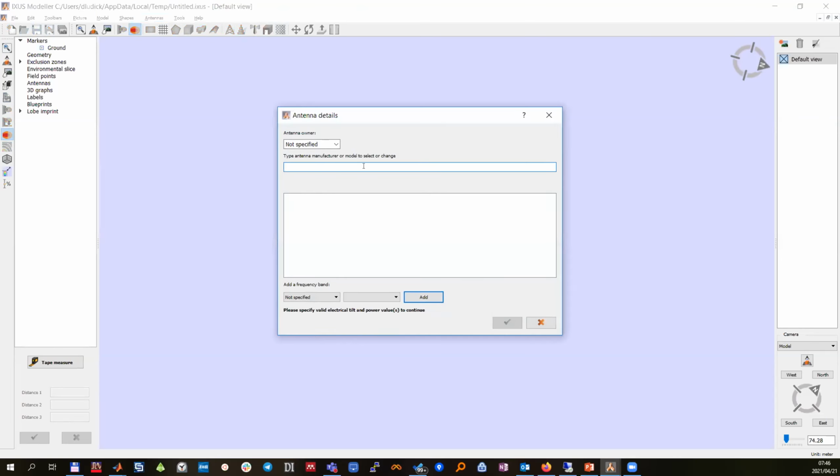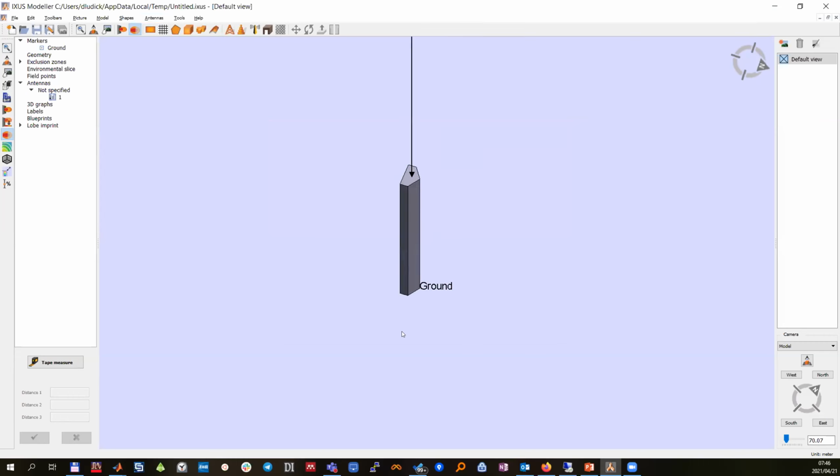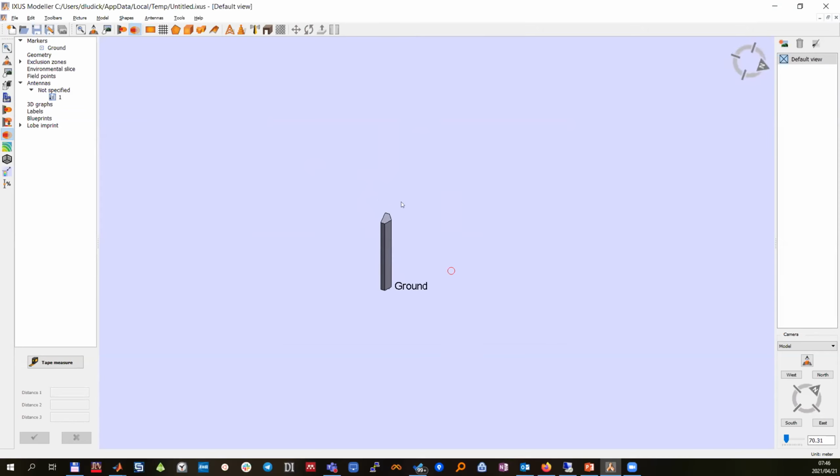Okay, so first thing, we're going to add our IEC model, no tilts. I'm just going to give it 90 watts of power on each of the ports, and it's simulated at 900 megahertz. So we're going to place it here, just on the ground marker. Very simple structure like this. For the sake of illustrating the features, I'm not going to add buildings and geometries and all these things. I merely want to focus on the fields and also on the sampling of the fields.